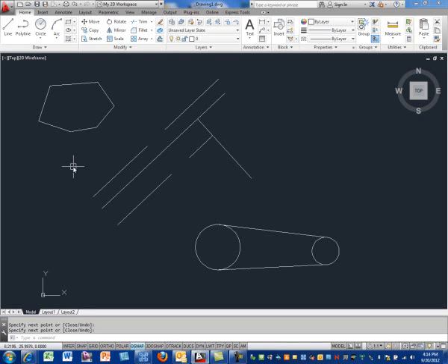Civil students or civil engineering students will need to use that feature more than others because they're going to be snapping to nodes or snapping to points because they'll be downloading point file data and it comes in as points, and then you manipulate and draw over the top of that data on the point files. These are some of the additional Object Snap features that I wanted to go over with you. Please let me know if you have any questions, and this ends the presentation.